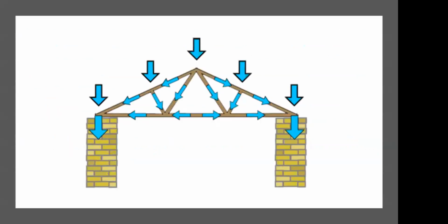Now if you see the diagram, all of you can clearly observe that there is an external loading, the blue color load, which will act only at the joints. Because of the loads at the joints, in between the triangular members there will be tension and compression, which will be transferred to the end points through the pin jointed trusses.